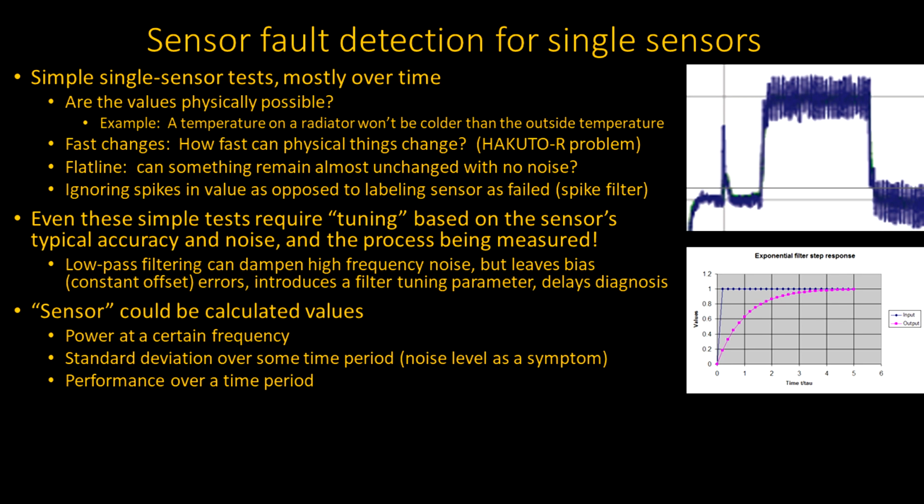Now, you can knock a lot of that out with low-pass filtering. It can be done. However, you have to be aware that the heavier the filter, the more of that high-frequency noise you dampen out, but you also slow down the response of your diagnostic system.